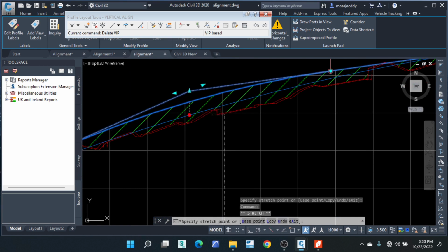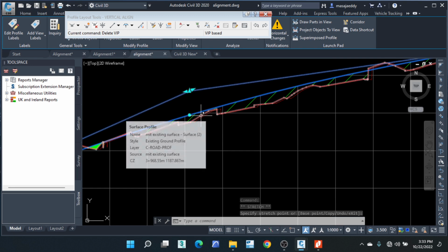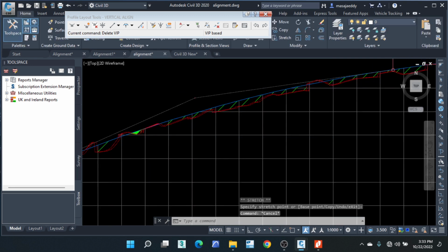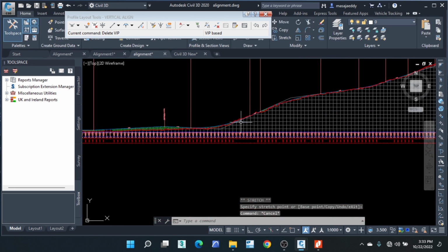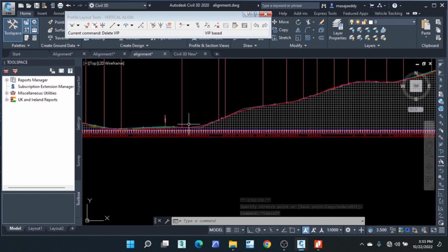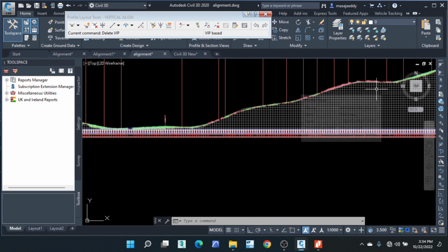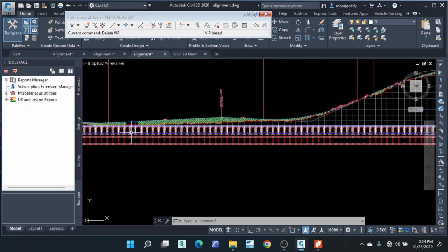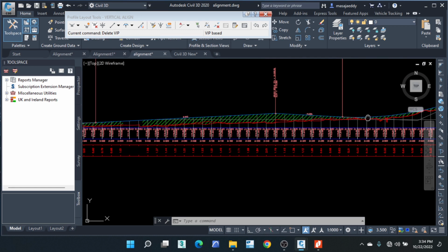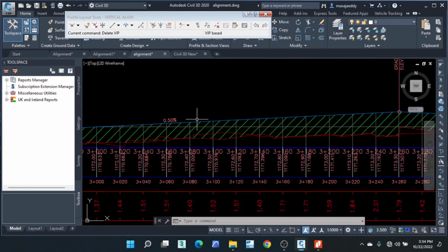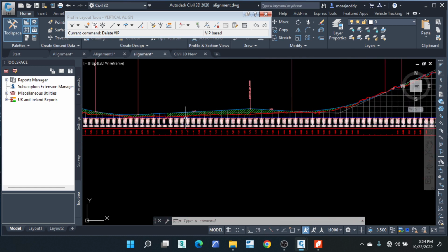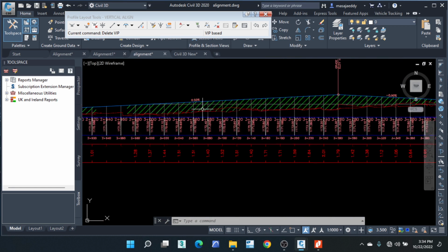I'm sorry, I have to come here, but I'm not understanding what you're doing. I'm trying to smoothen our vertical profile because if it has many curves along the length, it will have bumps along the road. So I'm always trying to create a smooth profile. And also trying to provide for the culvert. Now this is a pillow point. By trying to provide enough fill for the culvert.